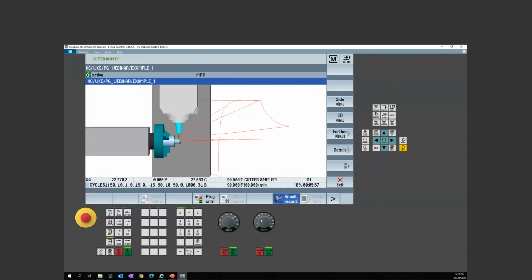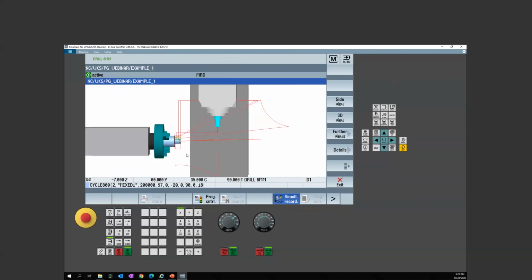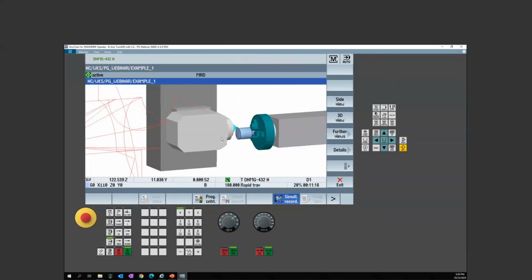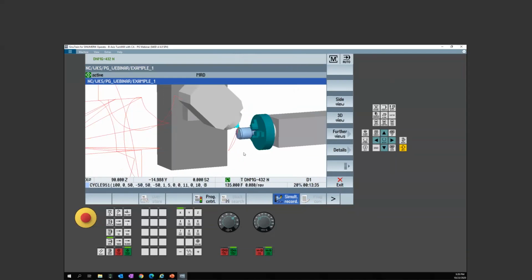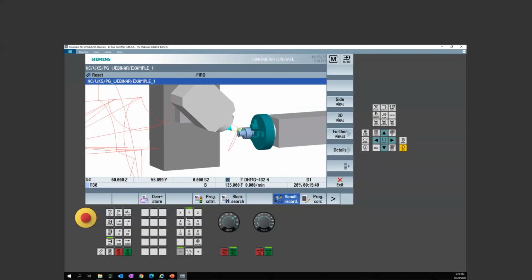All right, so there's our first flat, second flat. Here's going to be our drill. Drill comes in, drills the 4 holes. There's our transfer. And now if you look, remember I programmed 0, it spun it to 180. So that head 2 handled that. And then I kick her up at an angle. I only told it 45, it really went to 135. Again, we're letting the control handle that. Now it's obviously sitting here because of my M30. I didn't have any kind of clearance, so I'll just jog her up out of the way.